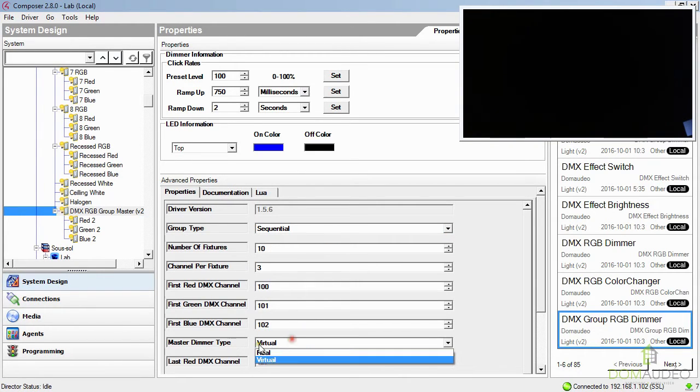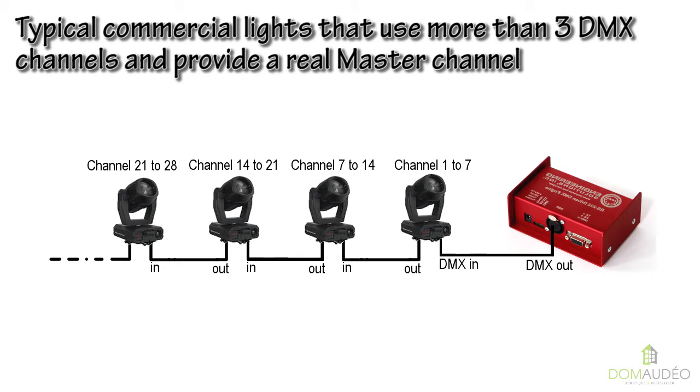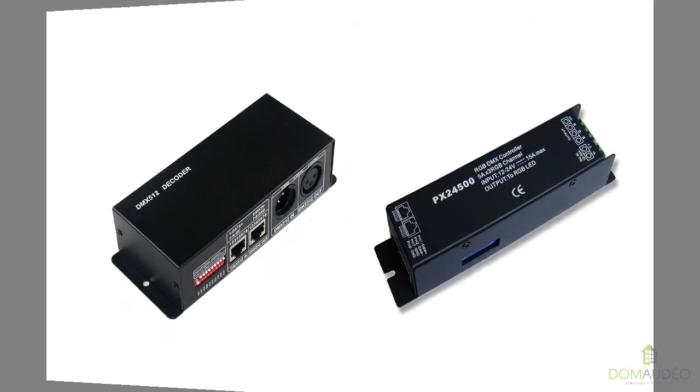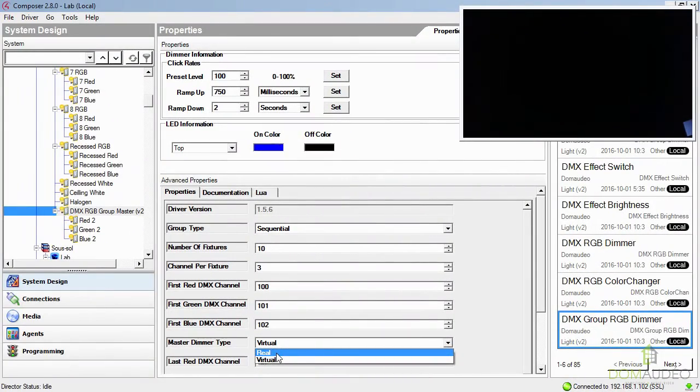Here we have the master dimmer type available. This property is used to determine if the master dimmer is a real DMX channel or if it will be simulated. A real master channel is sometimes called master brightness and is usually found in commercial lights with DMX built in. Most systems that use an external DMX decoder will not get a master dimmer, so this is why we have the option to simulate it.